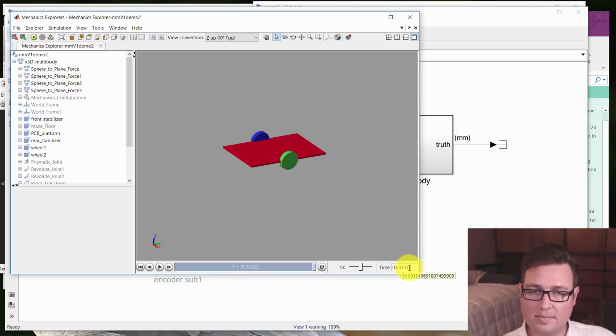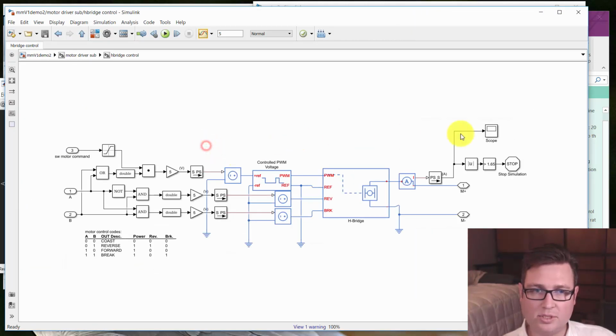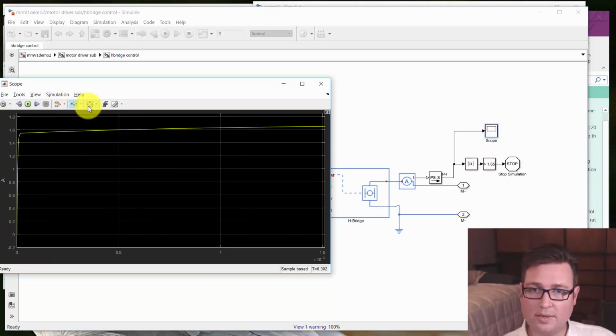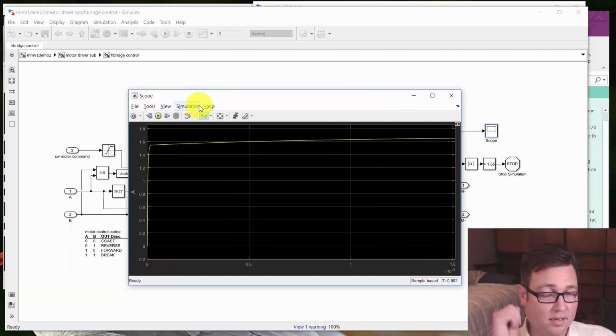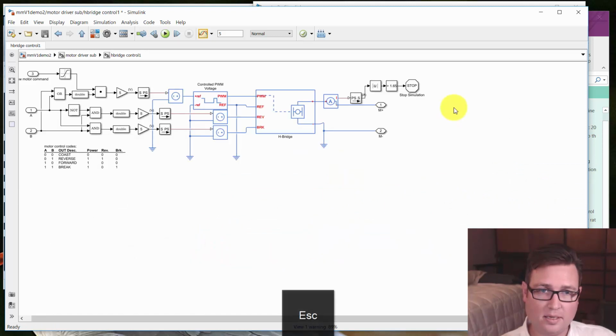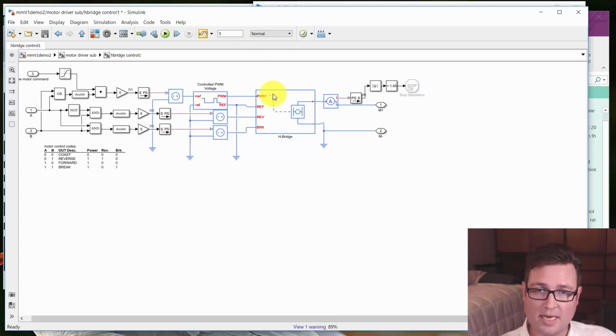Well, I didn't like that because I think there was a jump in current, I'll bet. Let's double check and see. Yep, there's a jump in current. So the combination of our dropping it and our giving it a step command put us over the edge. So for the moment, I'm going to comment this out, the stop simulation part of it, because I think that's going to pass, and I think we learned a lesson that we needed to learn there.